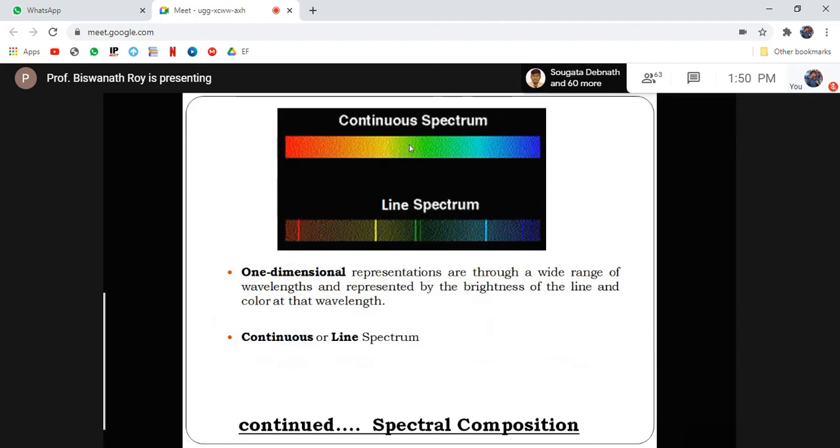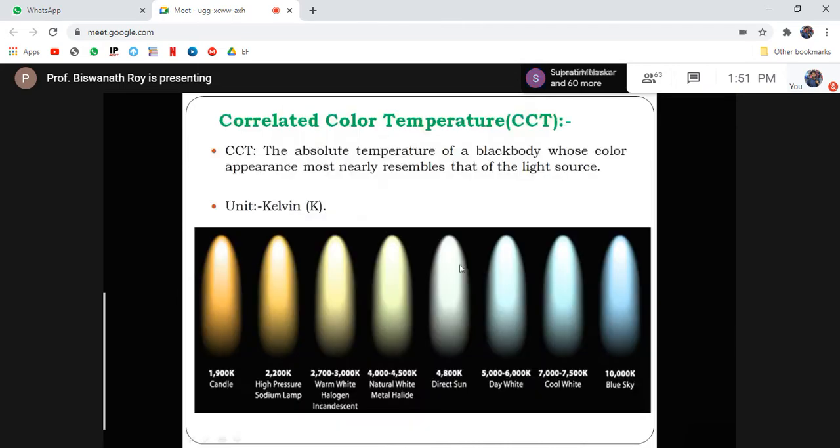So what is the purpose of the drum? There is a mechanical arrangement. When you rotate the drum, it rotates the prism with respect to the z-axis. When the prism gets rotated, the angle of incidence changes, so we can select different colors and bring them to the axis of the telescope.